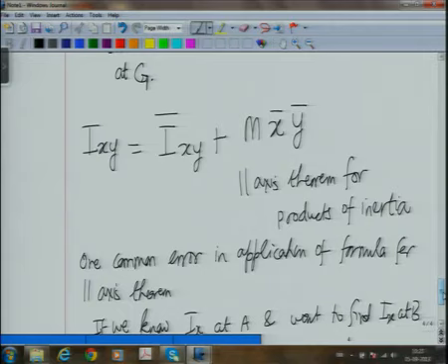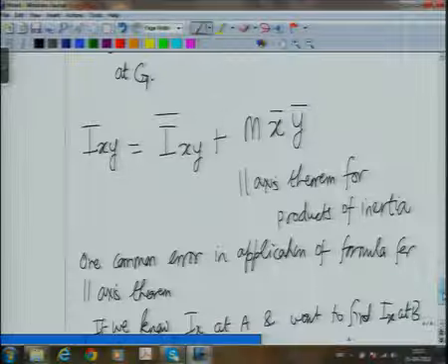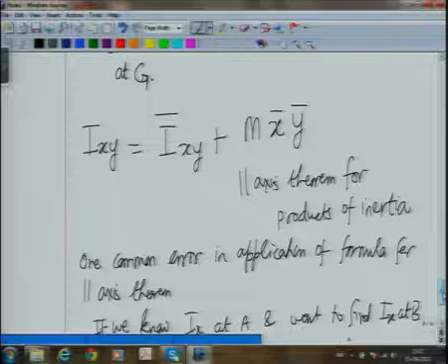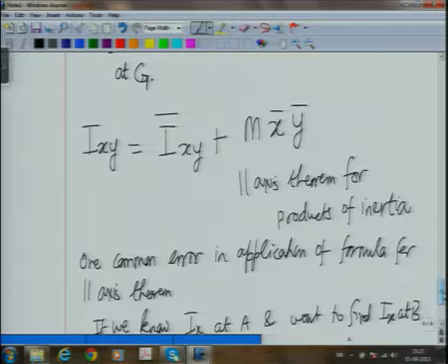That means you write what is x bar, y bar, z bar, you write what is I about these three axes, and write the I about the new axis. Calculating the distance between the two axes is straightforward if you are shifting only along one axis, but if you are shifting along two, then you have to take the square of the distances along both axes, which may not be obvious by just looking at the picture. So then you should just use the formula. Okay. So this is moments of inertia.